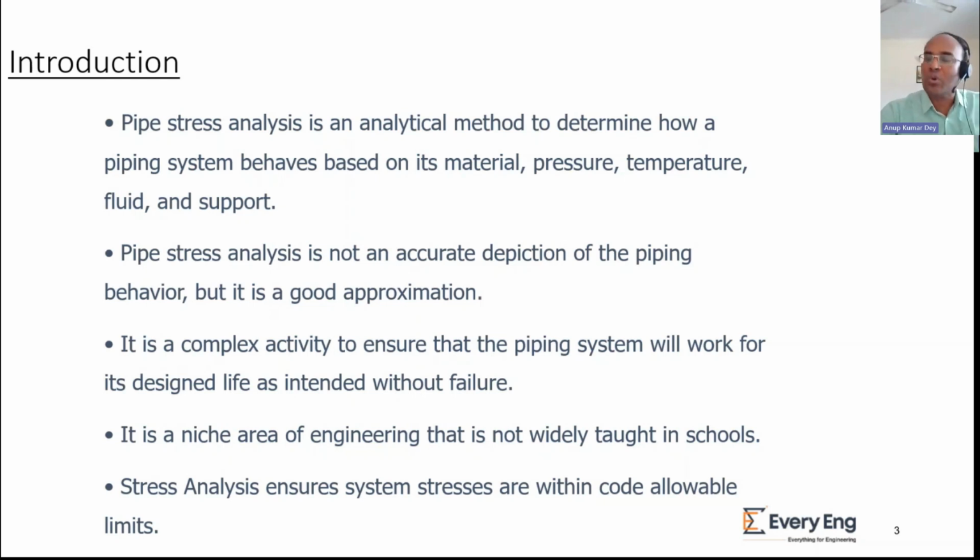This way, one more load case or temperature case we can prepare. And in the software, there is an option to provide up to 9 temperature cases. Now, if your program or system has more than 9 temperature cases, then we can analyze that in two files. Then fluid properties. So we have to provide the fluid density and then supporting.